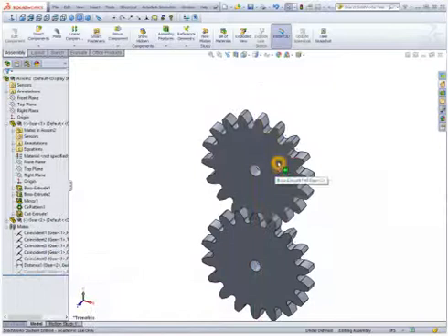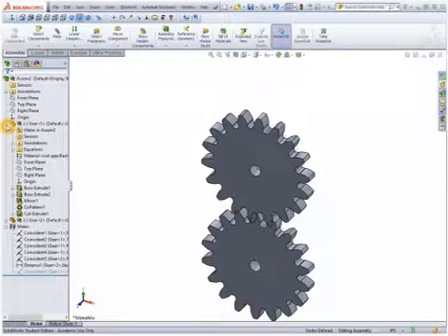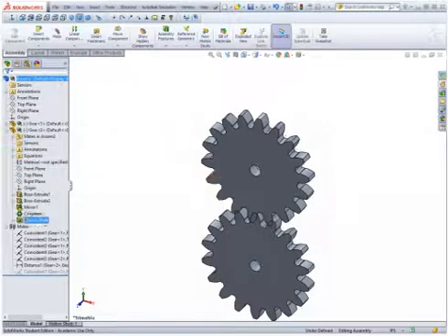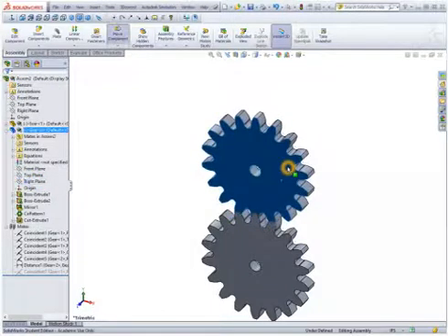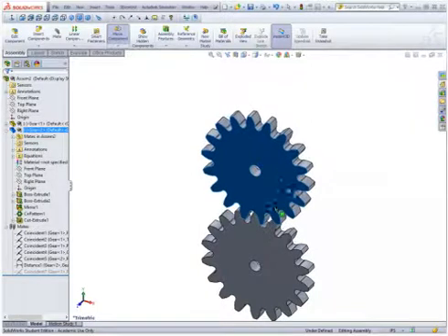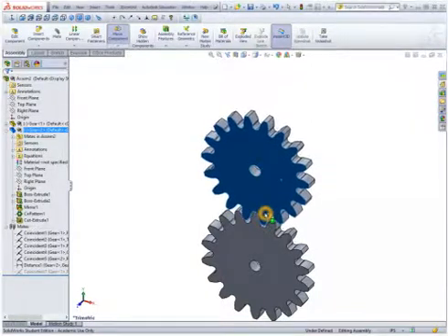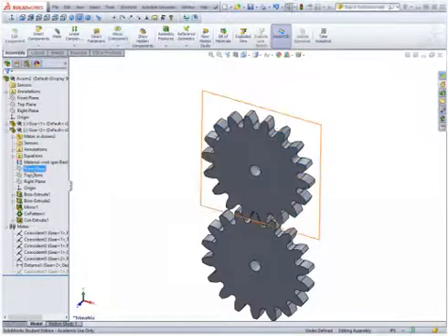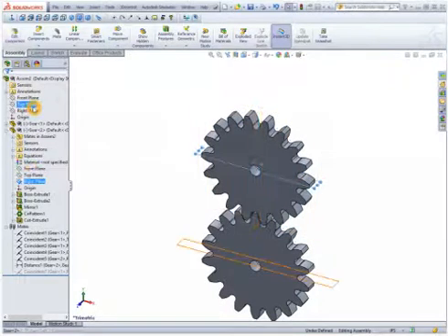We'll do the exact same thing for this gear, but you'll note that if I use that right face and make it parallel to the right plane of the entire assembly, the two gears won't line up. If I rotate this gear to where that's perfectly vertical, the teeth actually intersect. I want that to be one step over, or in this case, I can rotate it 90 degrees. And I can make the right plane parallel to the top plane.